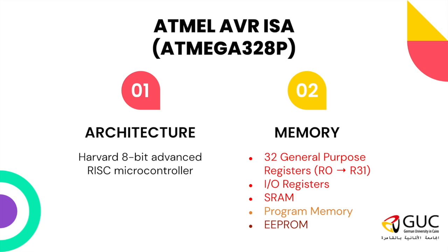Even the data memory and the registers all store 8-bit data. However, here in the program memory, we have a totally separate memory, which is a non-volatile memory. Take care, the data memory is volatile. If I unplug my microcontroller, everything in the data memory will be gone.